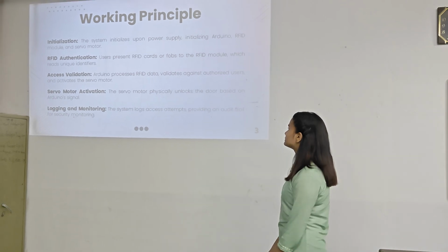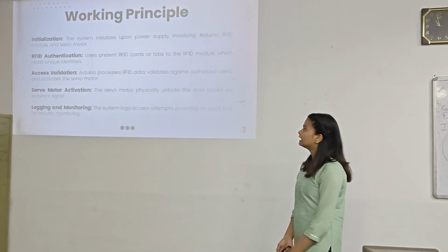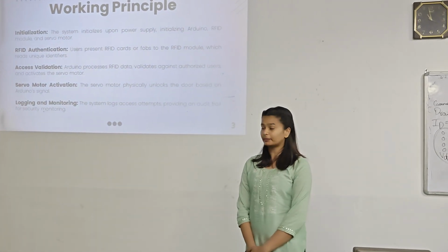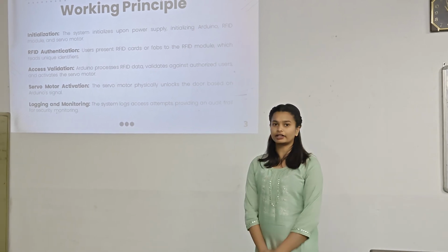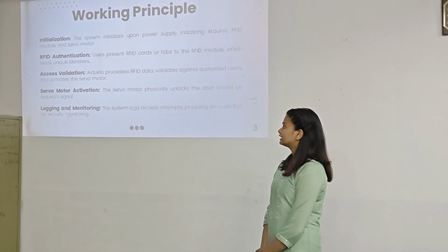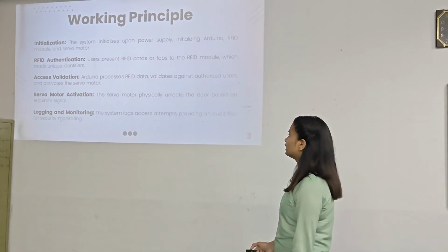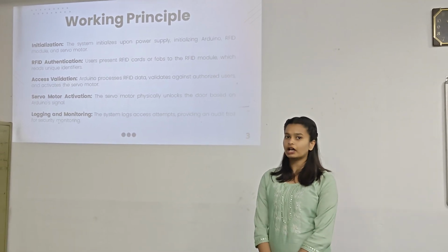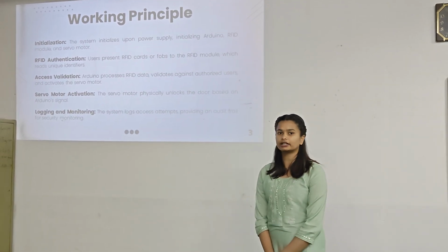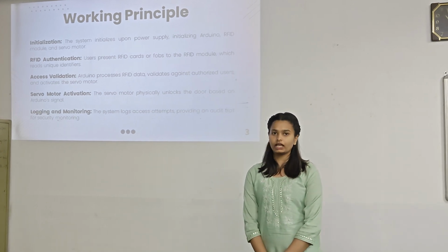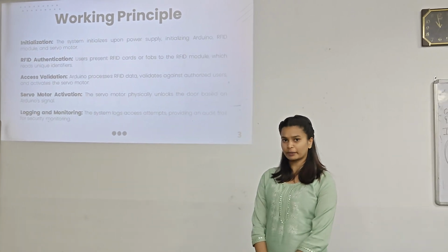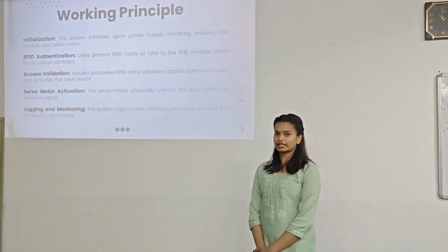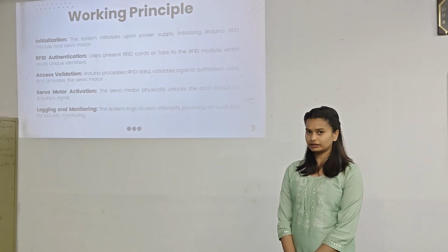Let's move to the working principle. First of all, initialization. The system initializes upon power supply, initializing the Arduino, RFID module and the servo motor. Then RFID authentication: the user approaches the door with the RFID tag. When the RFID tag is brought near the RFID reader, it gets energized by the reader's electromagnetic field, and the tag transmits its unique ID back to the reader.